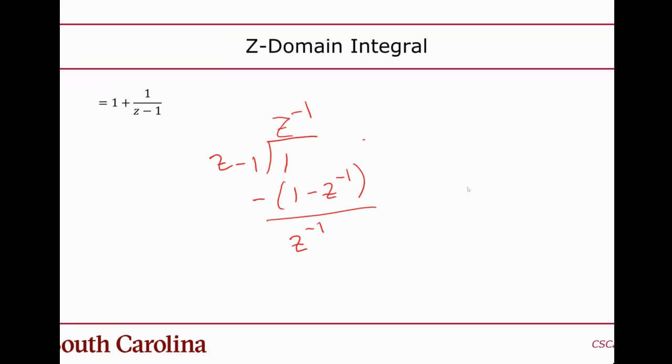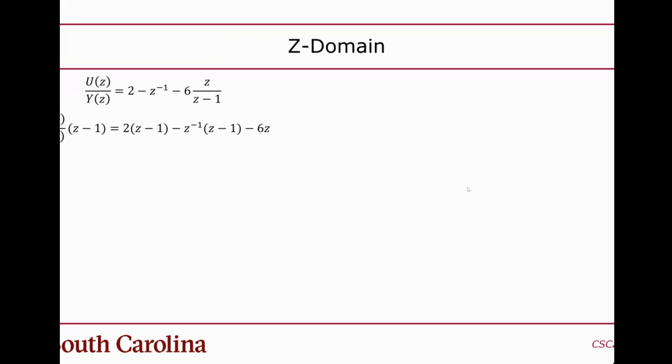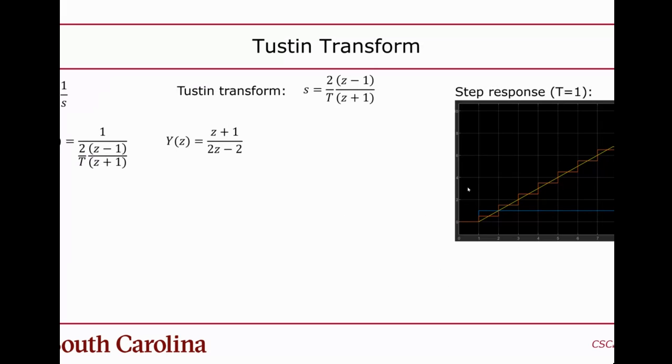And it turns out that works sometimes, but there's no guarantee that will work, is a problem. If you have a slow enough system, it'll work, because basically it'll mean that the processor is fast enough to make it not be an issue. But a better way to do it would be to convert the S domain transfer function that is modeling the plant. You can convert it to the Z domain. And you can do it.